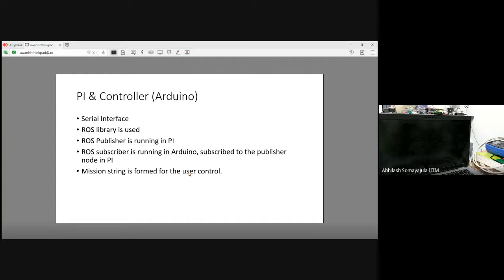I think it's better to keep it separate. Rather than asking to provide the Arduino with the speed of the vehicle, it is probably better to provide it with a commanded RPM. That is always better. You can always feed back the sensor information to make sure that it matches the required speed.